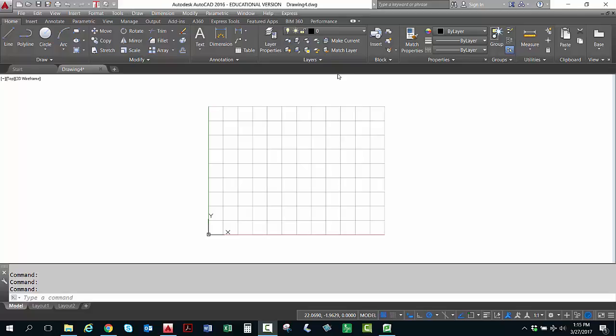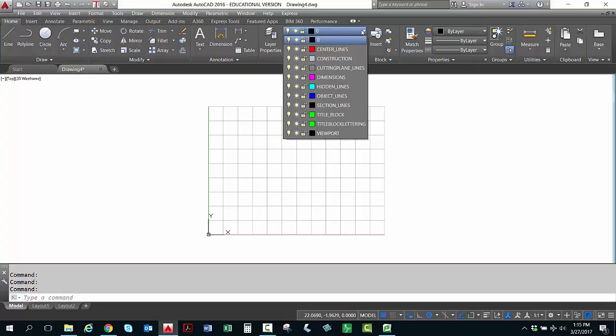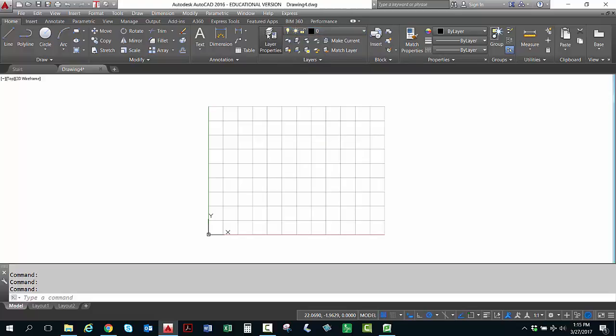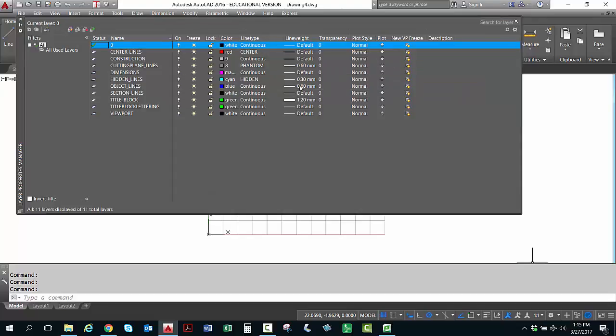Okay, I have now loaded, installed, and configured all of my layers, with proper colors as recommended in the book, and set their properties. Proper line weights for each layer and line types have been loaded. Okay, and you can see the plot style is all set to normal under the ACAD style table. Alright, so all that is set, and it says to set our construction layer current.